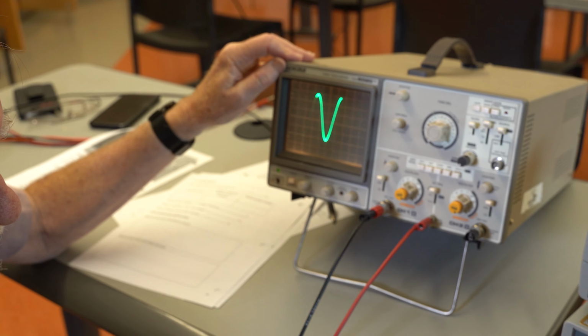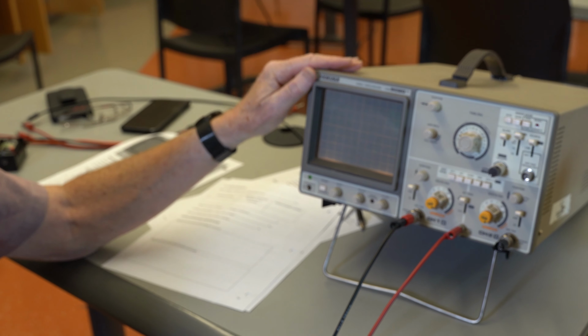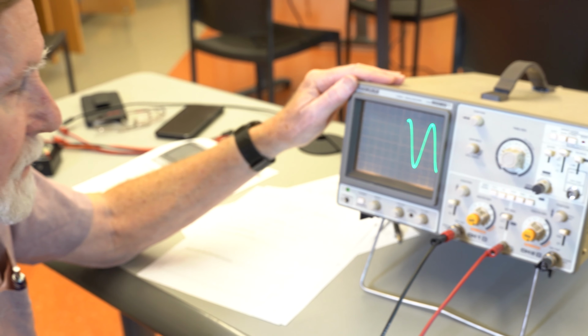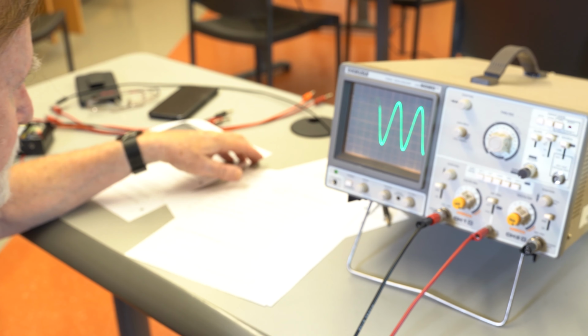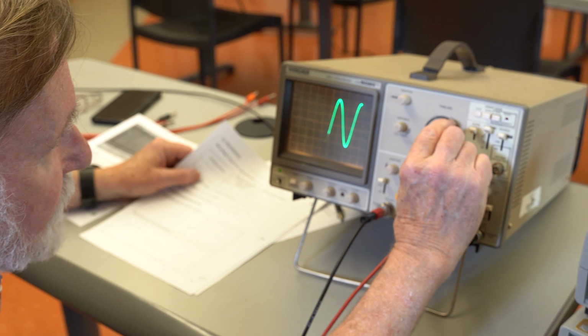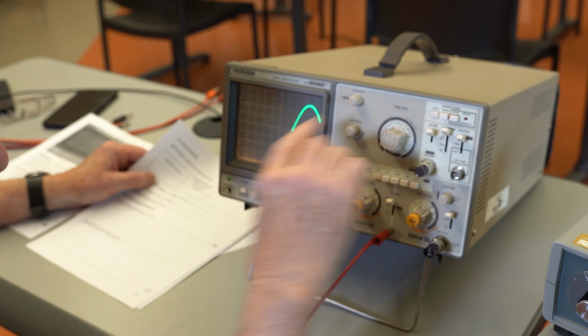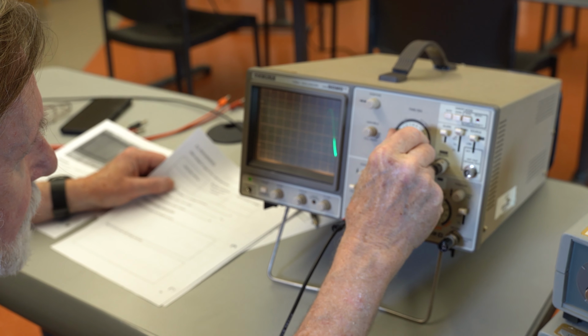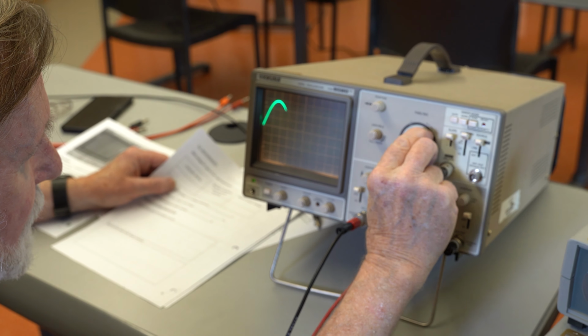And so this gives us a good idea of what the waveform looks like. That's one of the things oscilloscopes are used for, to check the shape of a waveform coming out of some electronic component. What controls this is how fast the little dot sweeps. Now it's sweeping faster, and so it spreads the waveform out. Now slower, and it's all scrunched up.